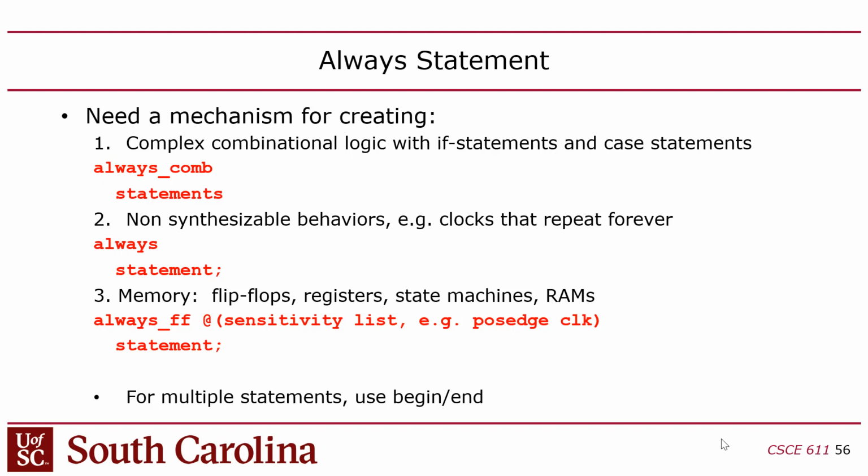The risk, though, of doing that is what happens if you say D and F. Well, now you've got F, which is treated like an input, but is not in the sensitivity list. So now this is memory. You're going to have memory in here, because whenever C or D change, that's going to act like a clock signal for reading F, and this turns into a latch.